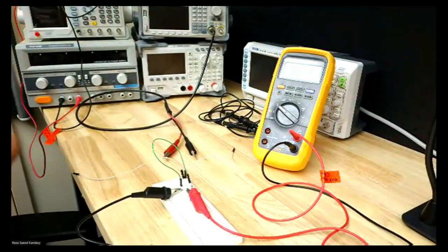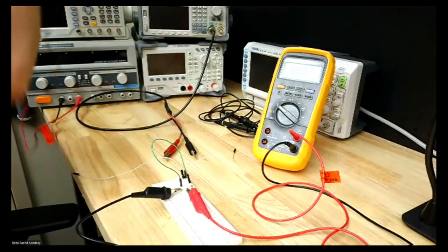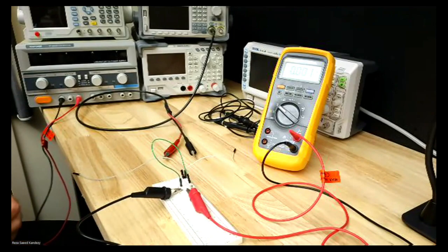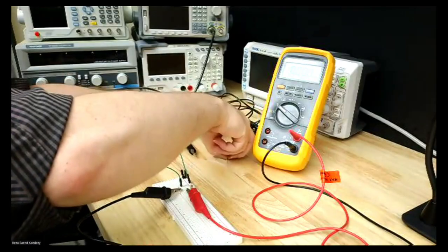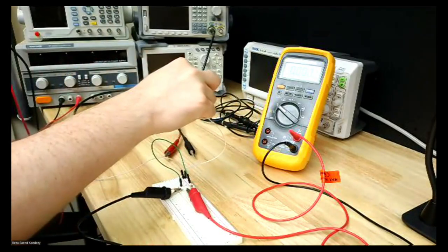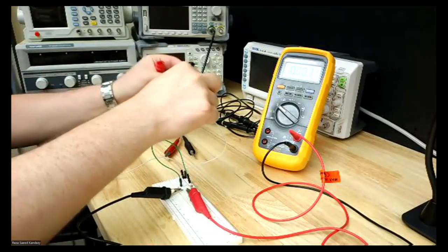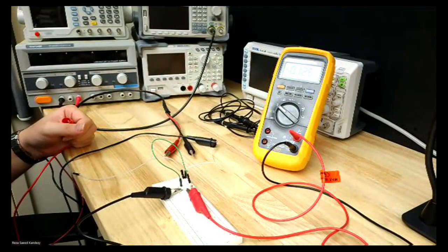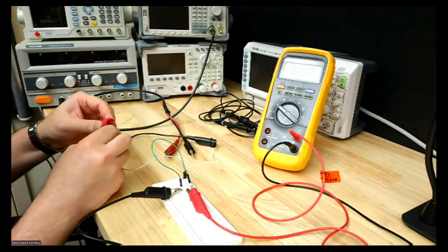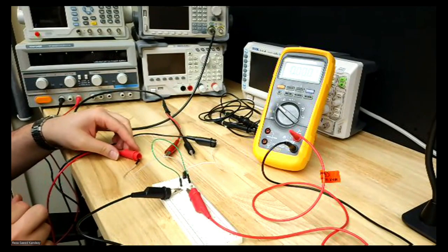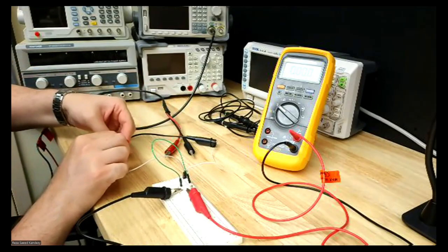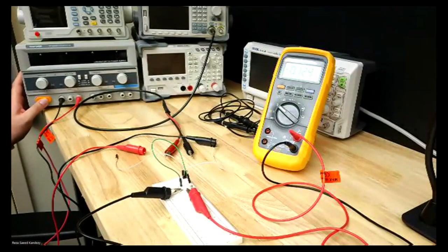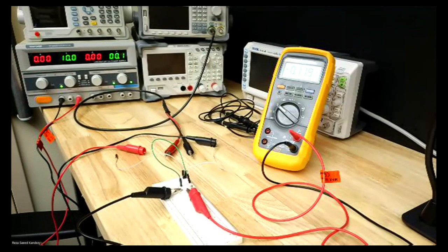Okay. Now I am gonna connect my DC source. And remember, we are gonna do the forward bias, so polarity is important. So I'm gonna connect the negative port of the DC source to the negative port of my circuit, and the positive one to the positive port of my circuit. Okay, now before I apply that, actually let's set the voltage and then apply this. Now we are gonna turn on our voltmeter, our DC supply.